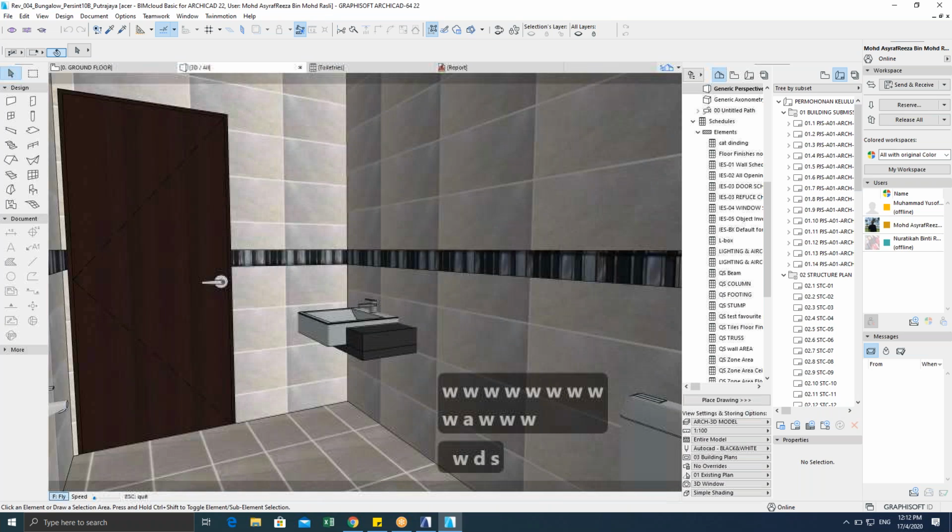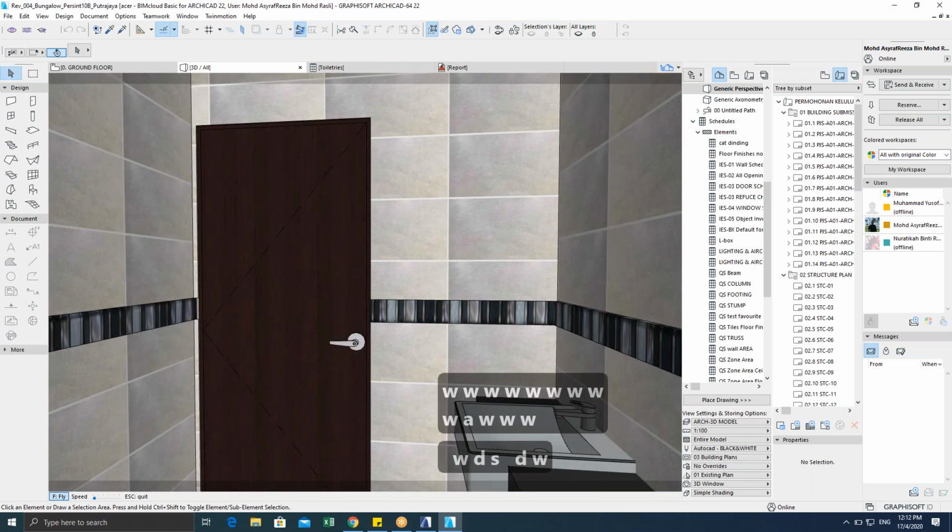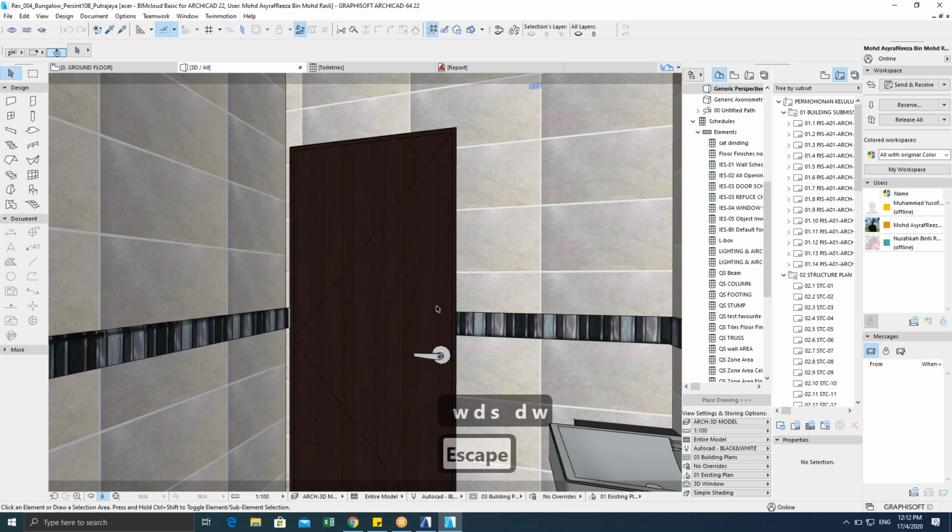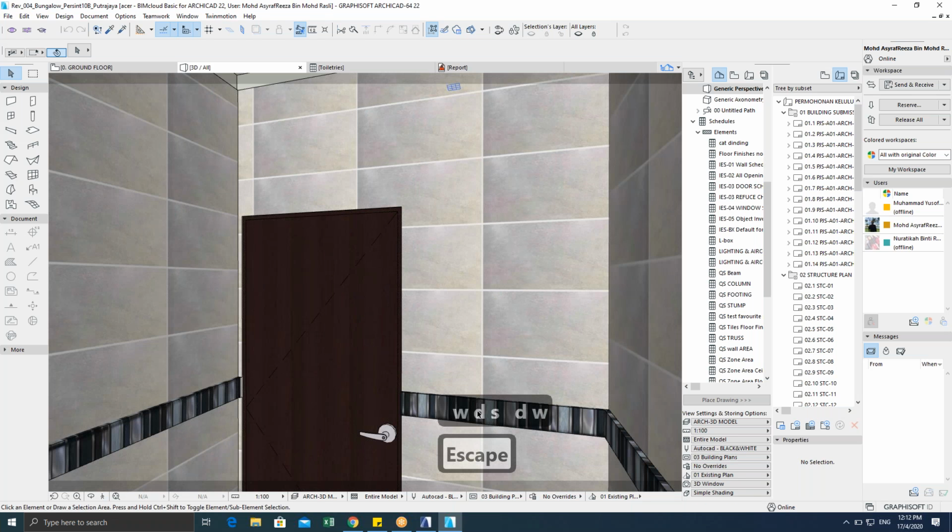Even as we know that under complex profile, we can create our own wall, something like this one. I have this different type of surfaces, right? This line, tiles with this another different type of tile. You can create that also for your own surfaces scheduling purpose, to know the quantity of your wall tile or your floor tile.